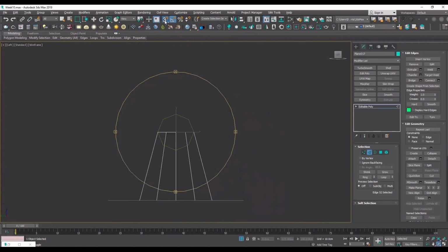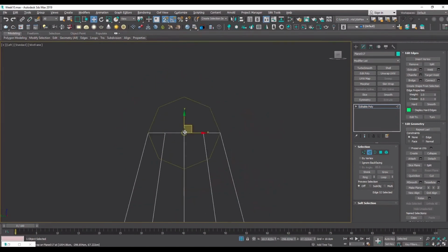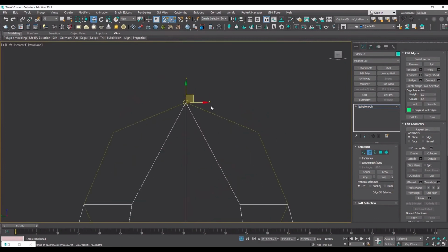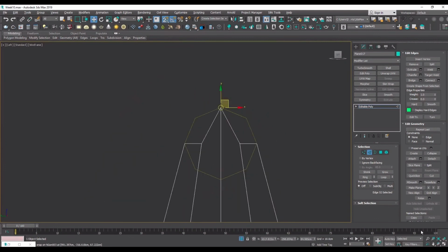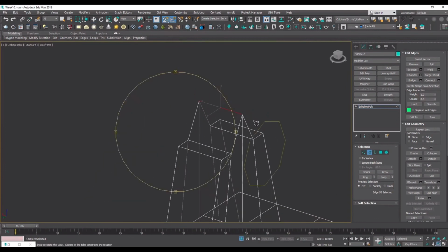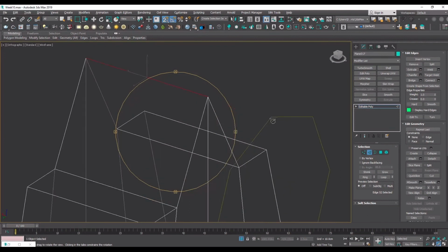But if you just move to a 2D orthographic view using the 2.5D snap mode, this time you will see that it's only moving in the directions, or on the axes, that we want, them being the y-axis and x-axis, and they will not be affected by the z-axis.